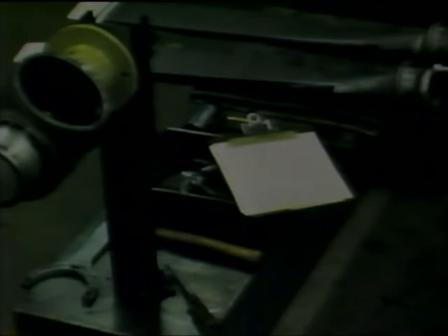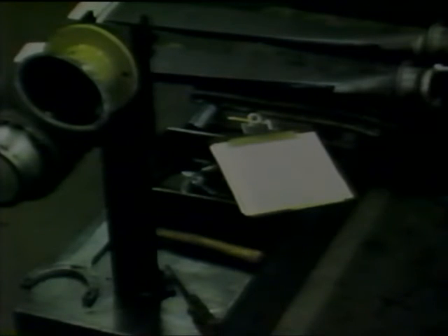During the pre-teardown inspection, documents are carefully reviewed and an accurate measurement of blade angles and track are taken and recorded on an FAA-approved form. As the propeller is disassembled, all related parts are inspected and recorded on the overhaul record. The parts are placed in small component trays where they will remain with the major structural pieces of the propeller as they move through the overhaul.